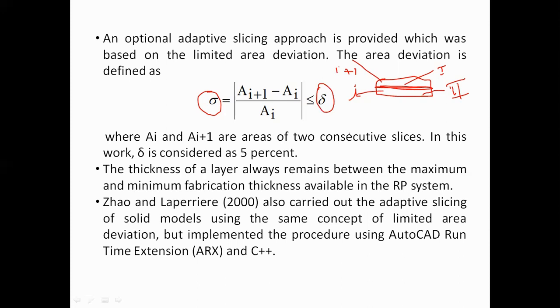I explained that when we were discussing the area method in the earlier lectures: when you are slicing, you may lose some critical features, and with adaptive slicing, due to a different number of slices and different zones, there is a loss of volume, generally because of shrinkage. That loss of volume is also going to be reflected in the cross-sectional areas of the two slices.